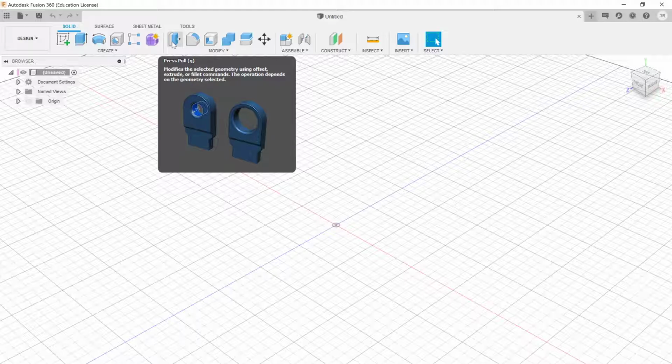This video we're going to focus on the Loft tool and the Sweep tool. They're very similar in how they're used. Their goals are to make 3D objects from sketches, very similar to what we've done, but they allow us the flexibility of transitioning between two different sketches. That's what Loft does for us. And moving a sketch along a path, which is another really powerful technique, so we can make exotic shapes.